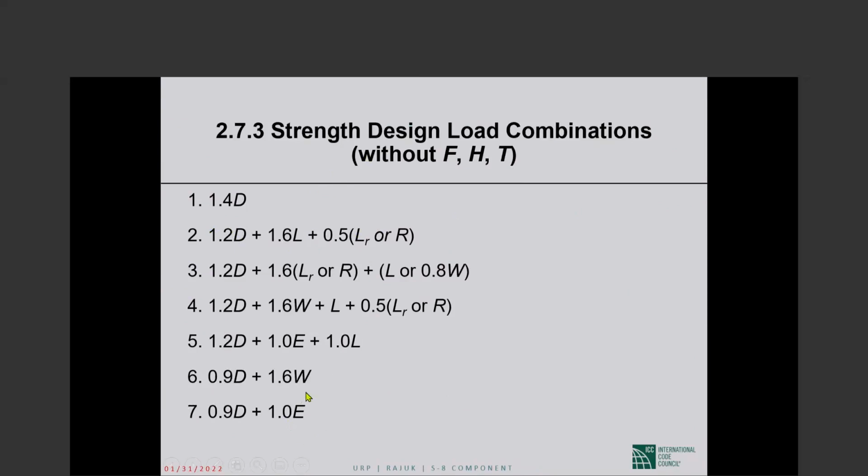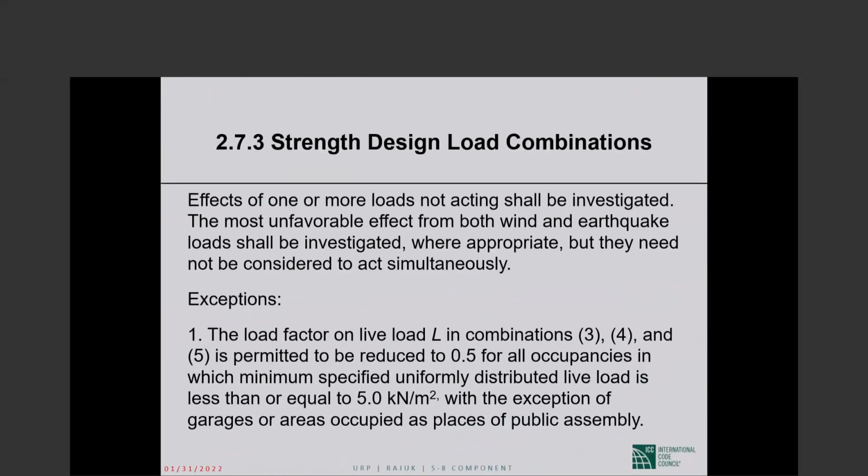You should also note that the load factor on wind is 1.6. Okay, so I will talk about that fairly soon. That number is kind of significant. Okay, 1.6 on the W.